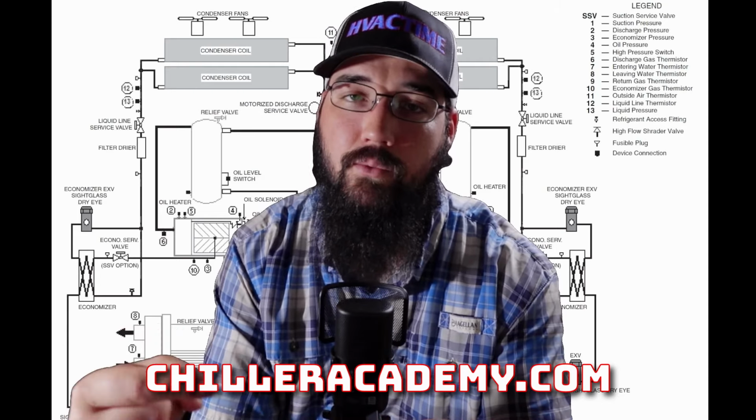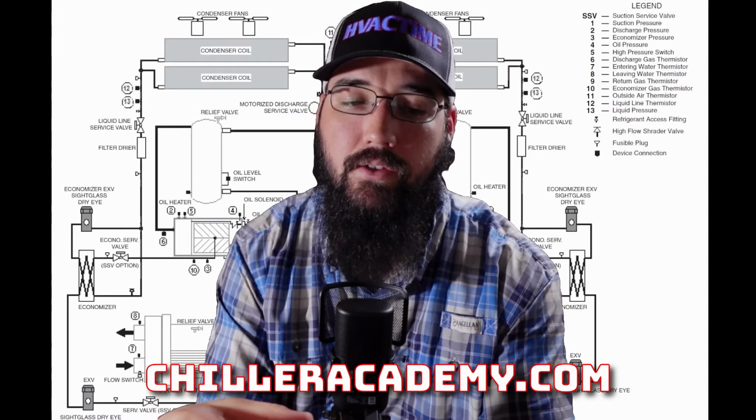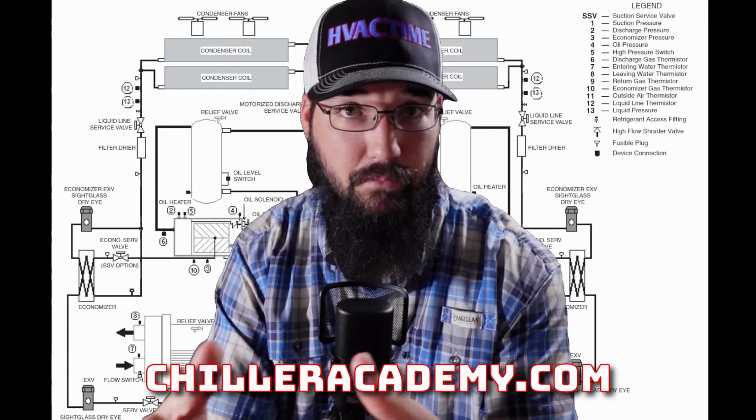The reason we're hitting our current limit is that the conditions on the compressor itself at that time are causing a lot of load on the motor, and the motor's having to create a lot of compression, with a lot of torque, in order to maintain the compressor speed.